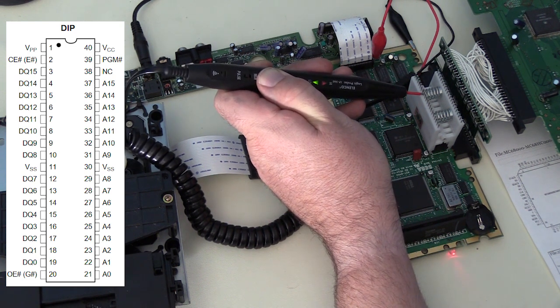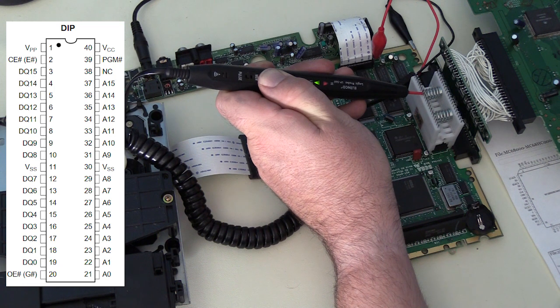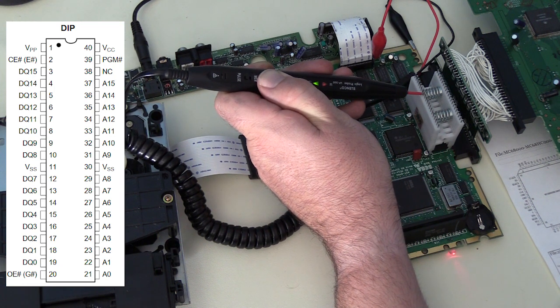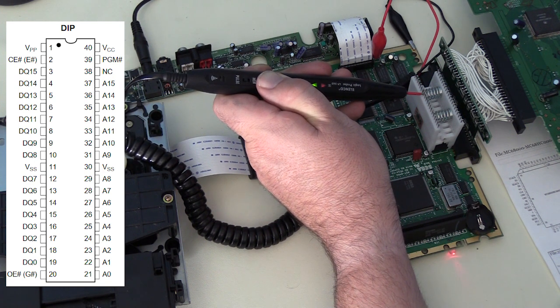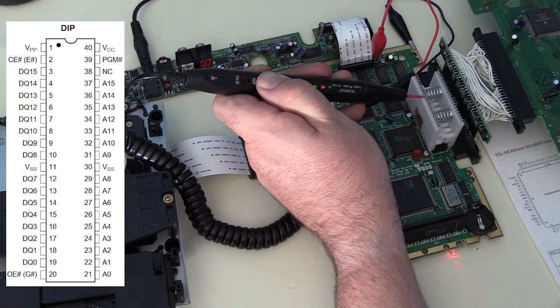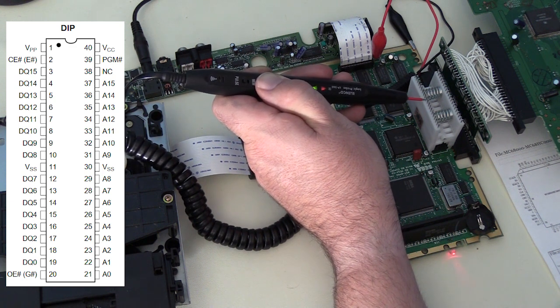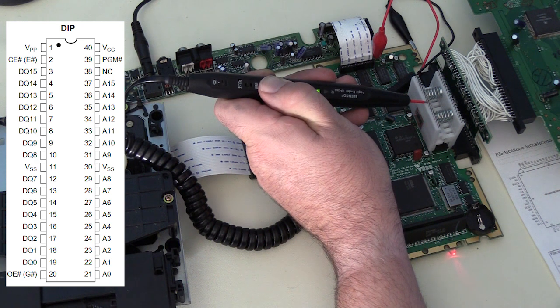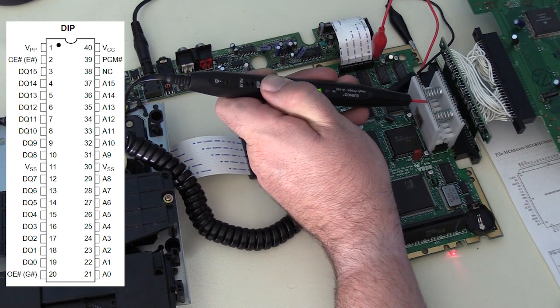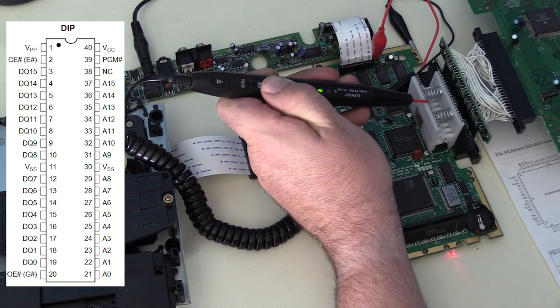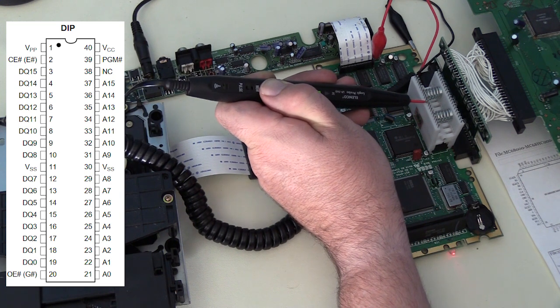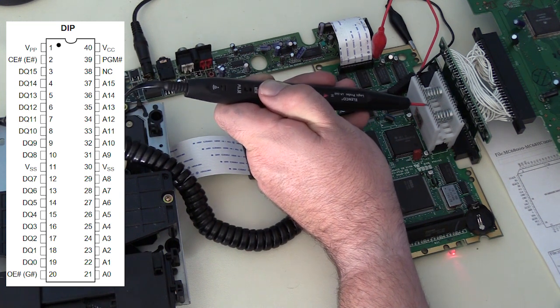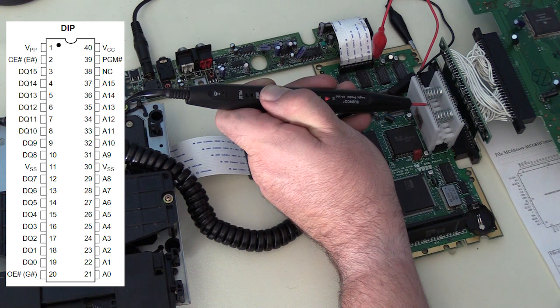When everything's working right, you should see rapid flickering between highs and lows on your address lines, your data lines, and the memory control lines, like the enable line. Okay, this one's holding low just because it's a ground. Pin 11 on the chip is a ground, so that's no problem there. Back onto more data lines. Activity there.